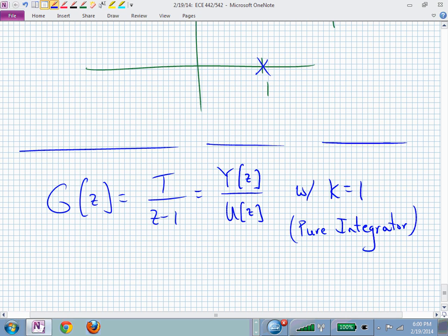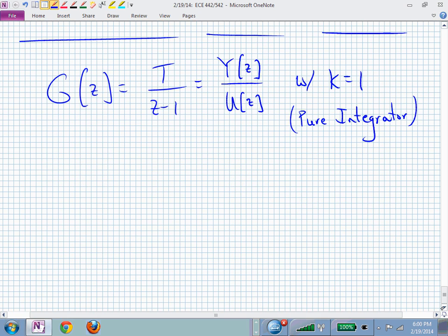So what's this going to look like in the discrete time case? Hopefully it will look like an integrator. So let's see if that's true. This now says if I now try to put this into a difference equation, I have z minus 1 times y of z. So I'm now just cross multiplying t u of z. That should be clear from exam 1 preparation.